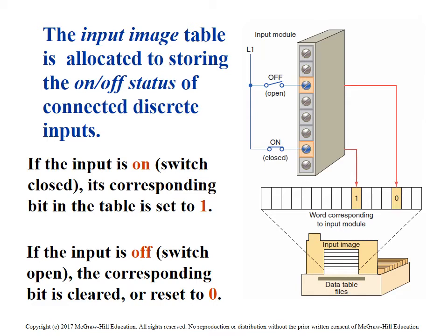So as we're making and breaking these contacts, or opening and closing these contacts, as you can see here, we have this contact here. When it's open, it's in an off state. That associated bit to that location, 0, 1, 2, of whatever word or slot this card is in. Associated slot word number is going to be the address location. So they didn't provide that here. We're just looking at bit level here. So here we're just looking at bit 0, 1, 2. 0, 1, 2 is off.